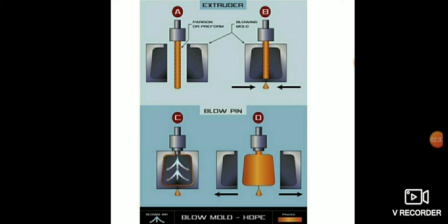The screw then rams forward via hydraulic or electric means, pushing the heated plastic through the head and out of the die head tooling as a parison. One of the most important items in blow mold design is for the designer to understand the plastic resin and its behavior in blow molding the required product.